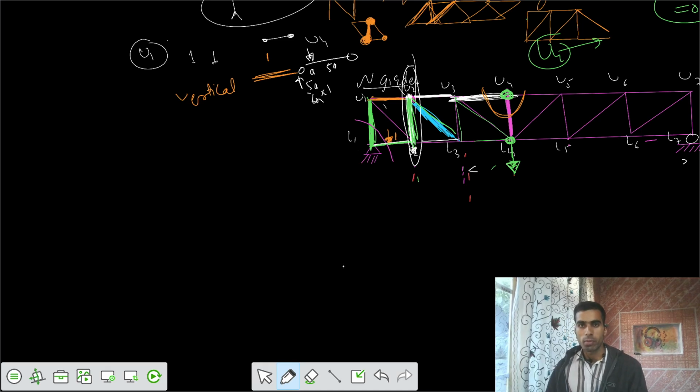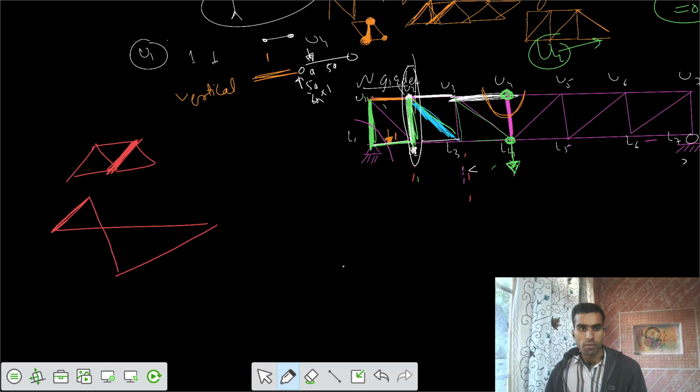See, when we performed that variant truss, when we are looking for that variant truss, I said if I take this member, what is the ILD of this one? I would say you orient it in this way. So if the start is in this way, that means the other side would be below the line. So you draw this ILD for this one. But if I talk about this member, what does the starting ILD look like? I would say you orient it in the same direction, in this way. That means the opposite side is above the line. So this was your diagram.